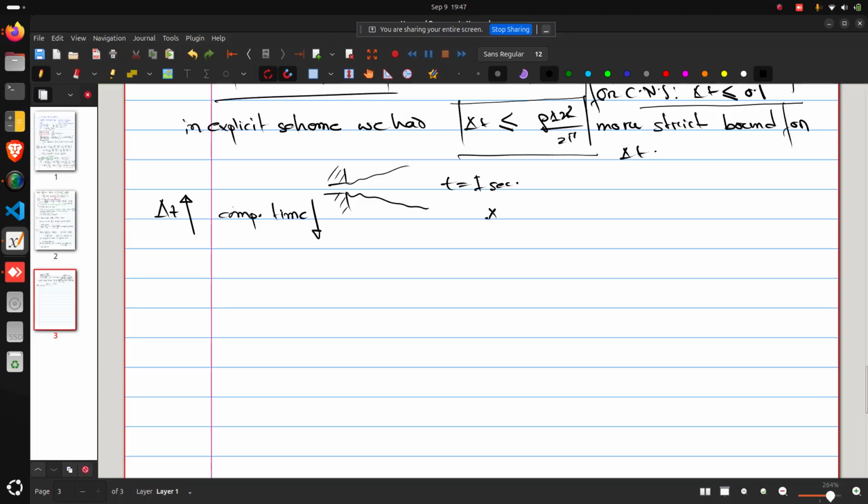If you take delta t value of 0.1, you can finish it in 10 time steps. But if delta t value is 0.05, you have to finish it in 20 time steps, right? So it will result in double the time of simulation that we need. At each time step it will take around some microsecond or millisecond.